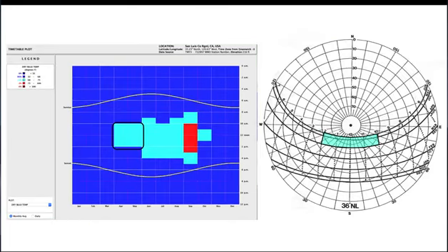So we're going to be working with our winter sun path chart. And we're not going to be worried about anything from December up to March because it's all too cold, which means we want as much sun to come into the building as we can. But in April and May, we're going to copy these times from 10 to 2 onto the sun path chart. So here's May, from 10 o'clock to 2 o'clock, I'm going to shade in that little block. Here's April from 10 to 2, I'm going to shade in that little block.